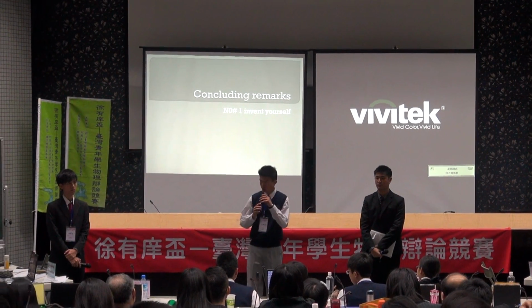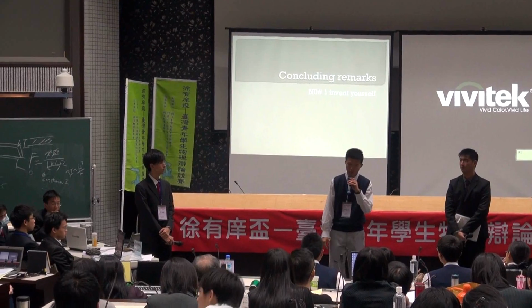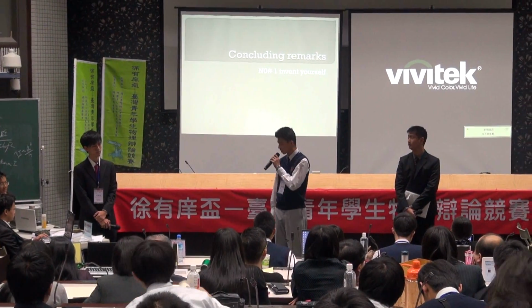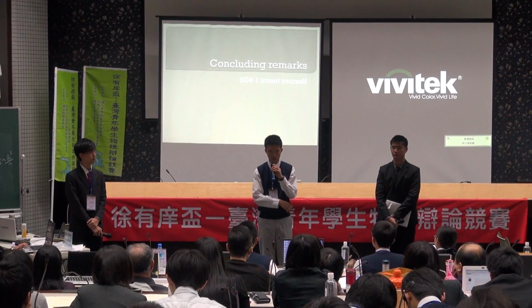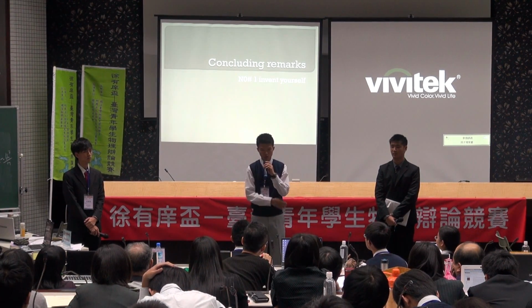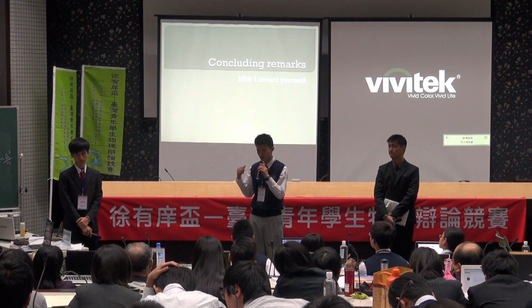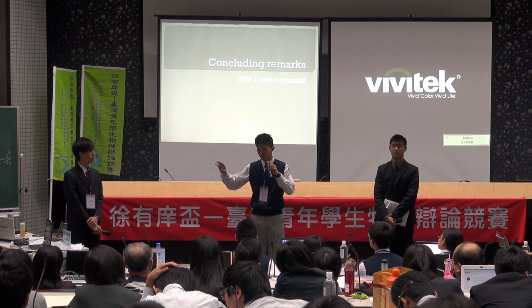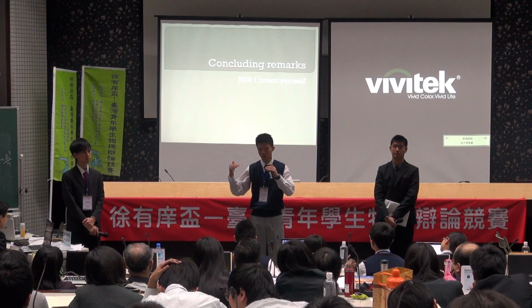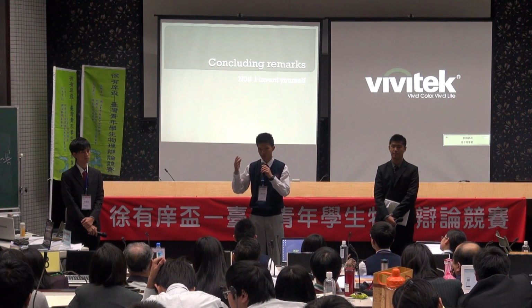In my experiments, I did 25 data points for each parameter, like each group. So we ended up folding around 900 to 1,000 pieces of paper in total. Among the 1,000, only a few used glue, just the last parts, like 200 or so. And I think the glue had 2 parts in the results. The first one, it increased the friction on the table, so it can withstand more force from falling down in the gap. And the second part, it increased the strength of the paper, just as the reporter said, but in a different way. We increased the strength, making it harder to bend.